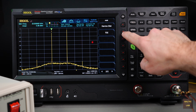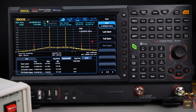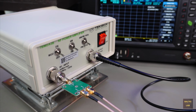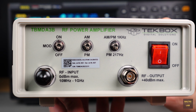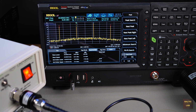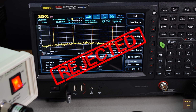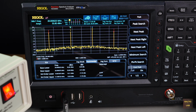The third-order intercept point is a critical metric for understanding an RF amplifier's nonlinear behavior. And in this video we'll measure it on the Tekbox TBMDA3B high-gain, high-power wideband amplifier. But there's a twist. The first measurement goes very wrong and falls below the expected datasheet value. Let's find out why. Before we troubleshoot, here's the essential theory.